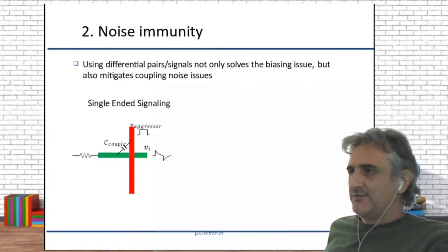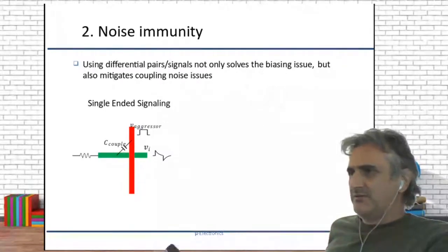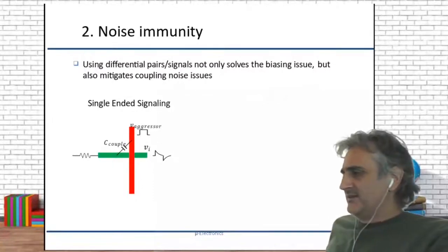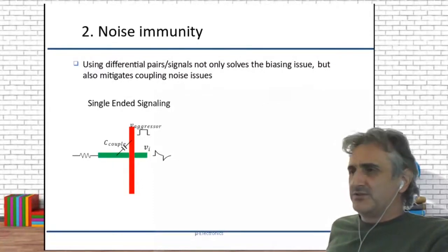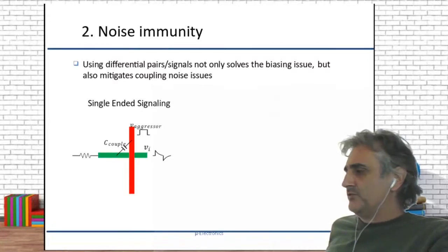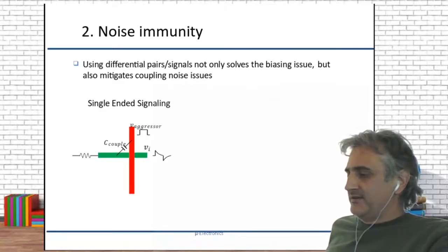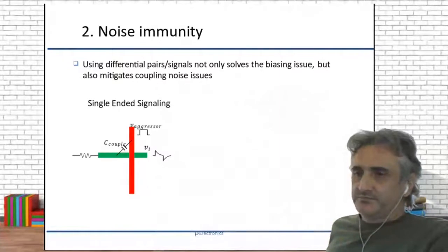For instance, assume that you have a line with a signal that is referenced to ground and has some influence by whatever. For instance, the value of a high resistor that is affected by an external electromagnetic field, or two signals that are coupled through a capacitor, as in microelectronic design.